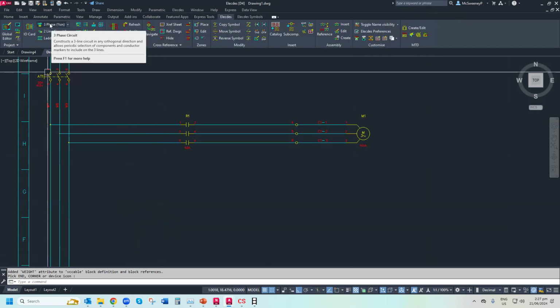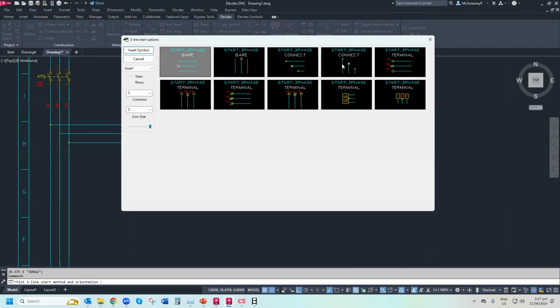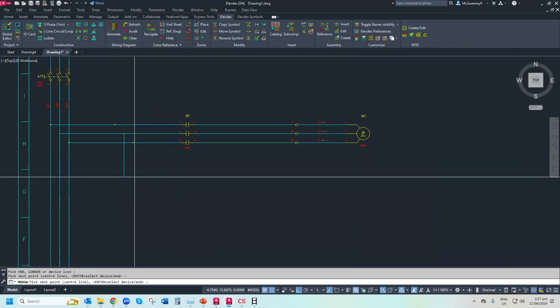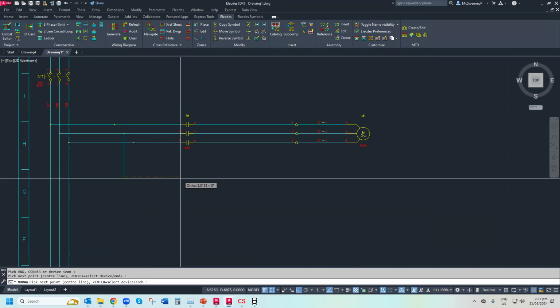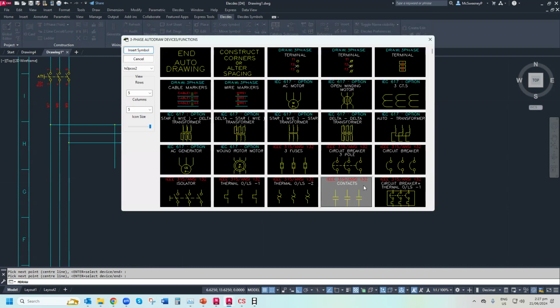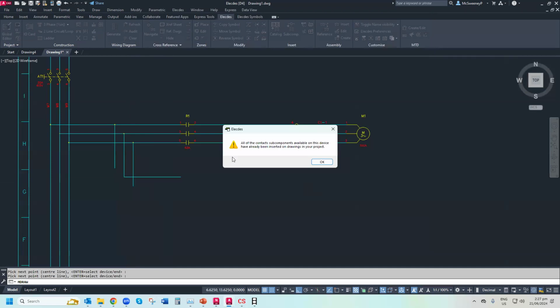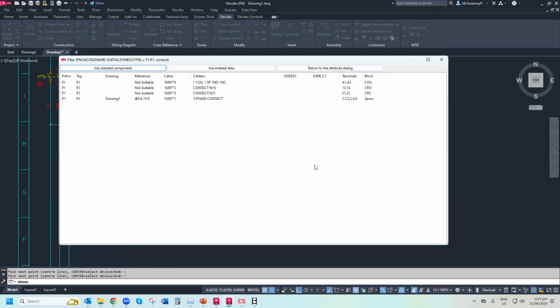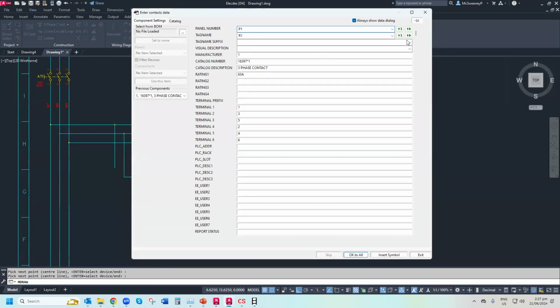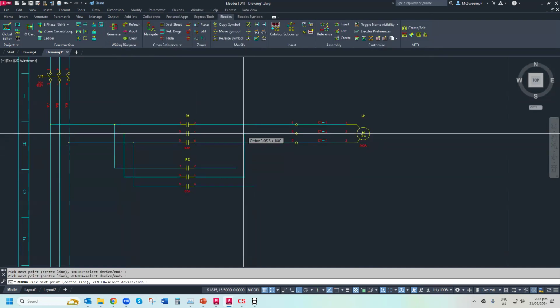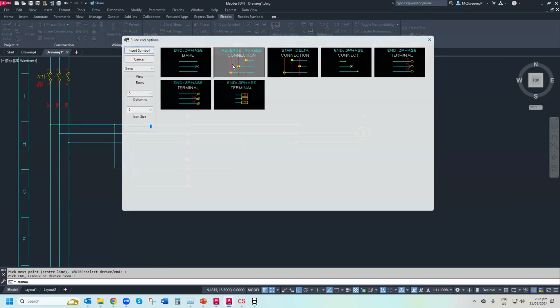Okay, and now again, I want to make this little fella go backwards. So again, how do I want to start it? Coming off the horizontal lines this time. Construct corners, alter spacing, down to there, across to there. Now again, I point out reduction of errors. I know I'm doing it on this drawing, but I might be on sheet 500. If I go and change it back to R1, it says, hang on a moment, it's only got one set of three-phase contacts and you've already inserted on that drawing there. So, oops, better not call it that. So again, reduction of errors, increasing in efficiencies. Okay, to that. Construct corners or alter spacing out to there, up to there, end auto drawing, reverse phases.